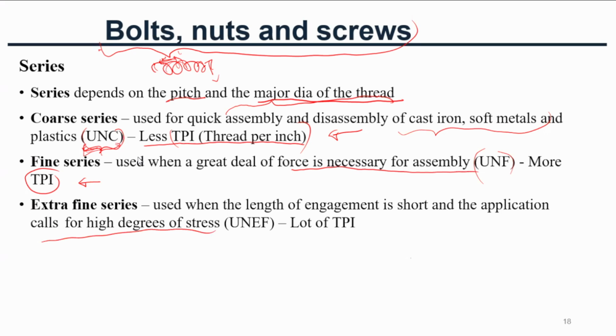Actually, we can always select these standard series based on material type, pitch and major diameter, assembly and disassembly conditions, and also strength. These are key items. Always select according to the type of material.